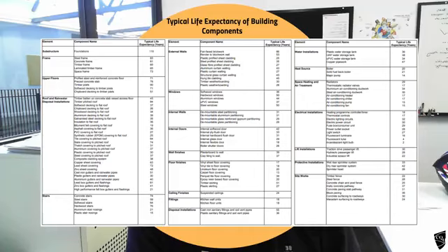Upper floors, you've got all the rainwater goods and different types of roofs, stairs, different types of stairs, plastic stair nosings, 15 years, a little bit on the very edge of the step. Well, from experience, I've never come across any that lasted that long. Aluminium stair nosings, yeah, maybe 15 years for those, but these, I wouldn't give them more than 10. But it changes depending on what the building is used for. So what might last 15 years in one building may last 5 years in another, or 20 years in another. It depends exactly what sort of use is going on.